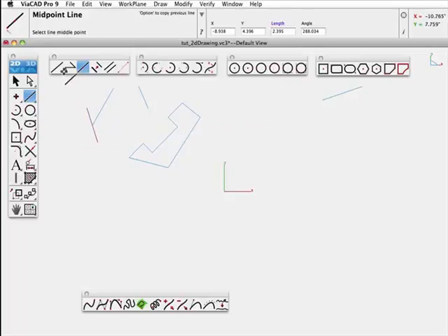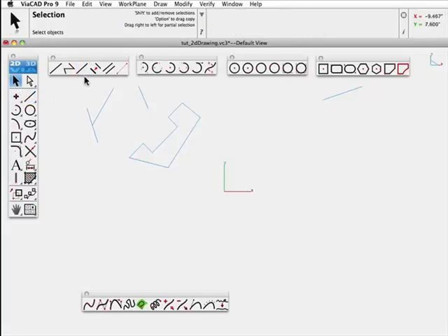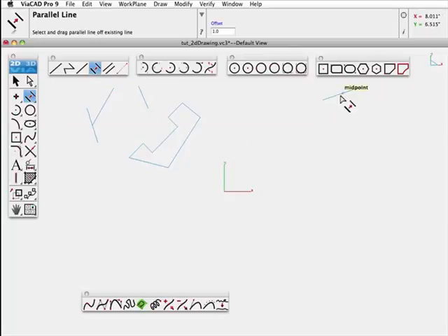Drag through the tool set, tear it off, and drop it anywhere in the workspace to give you quick access to the entire set of tools. The parallel tool allows you to drag a line segment and create a duplicate. Use snap modes to position the parallel lines. The parallel is an exact copy, the same angle, and even in the same direction from the original.